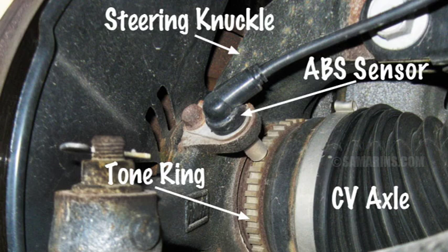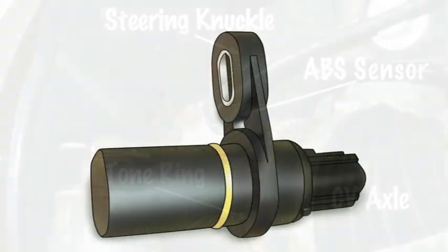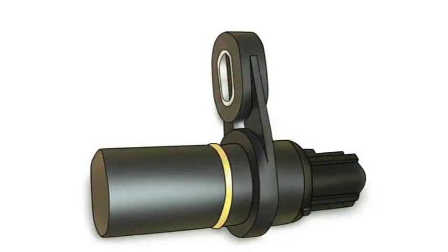Is it safe to drive with the P0720 code? It's generally not recommended to drive with the P0720 code, as it can cause further damage to your vehicle's transmission. However, if you absolutely need to drive, do so cautiously and avoid high speeds or heavy acceleration.